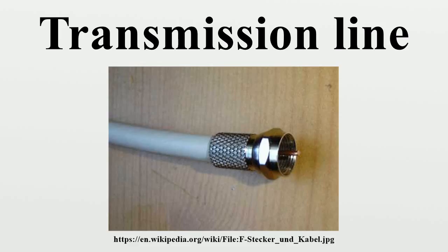This effect is called ohmic or resistive loss. At high frequencies, another effect called dielectric loss becomes significant, adding to the losses caused by resistance. Dielectric loss is caused when the insulating material inside the transmission line absorbs energy from the alternating electric field and converts it to heat. The transmission line is modeled with a resistance and inductance in series with a capacitance and conductance in parallel.